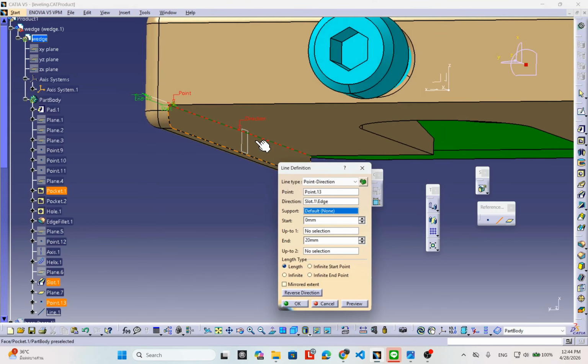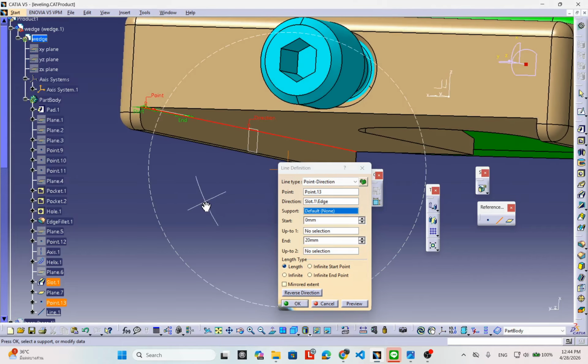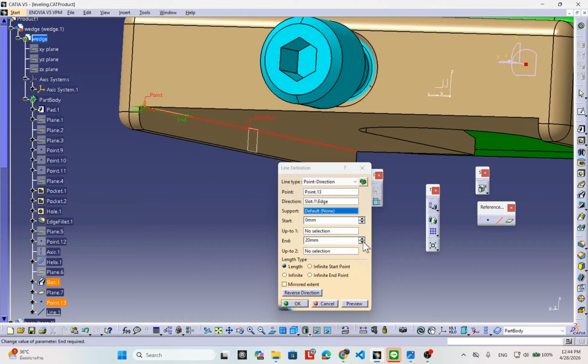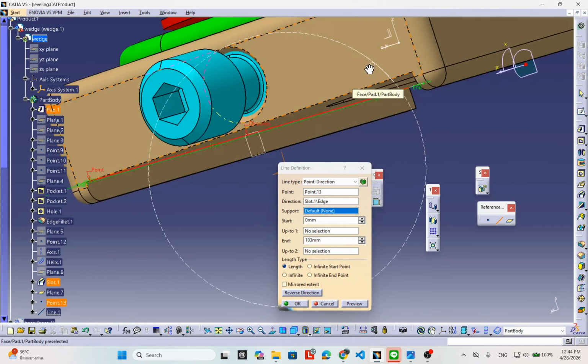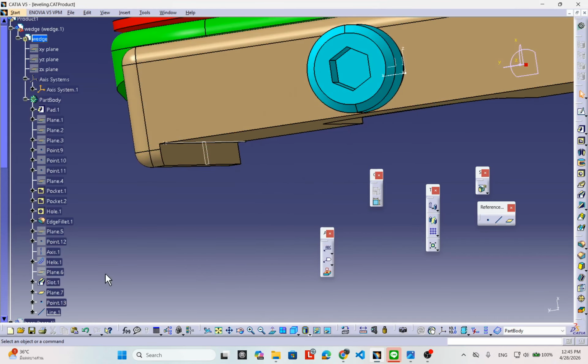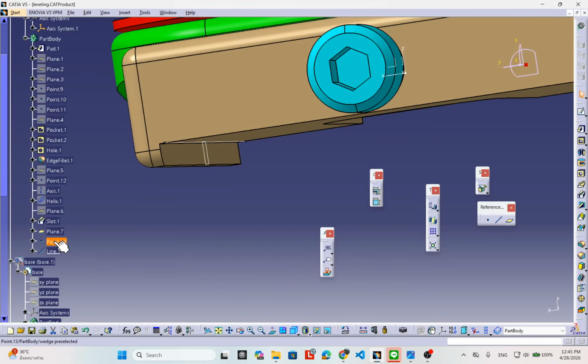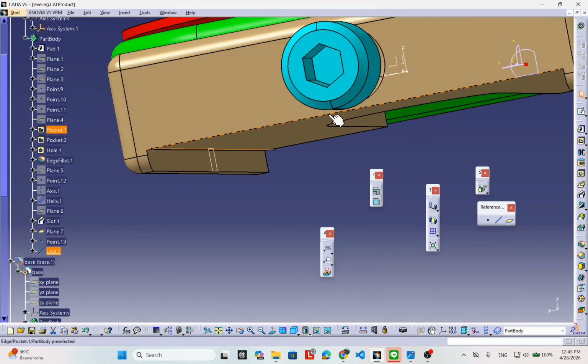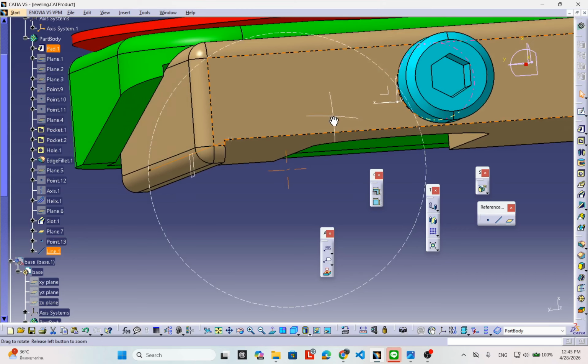This is the direction, and I switch to the opposite direction. Set up. Okay, the length, the edge, right. Okay, that's it. I got the line and the point, and the point and the pin. The pin and line are the parameters I need to use to create the prismatic joint.